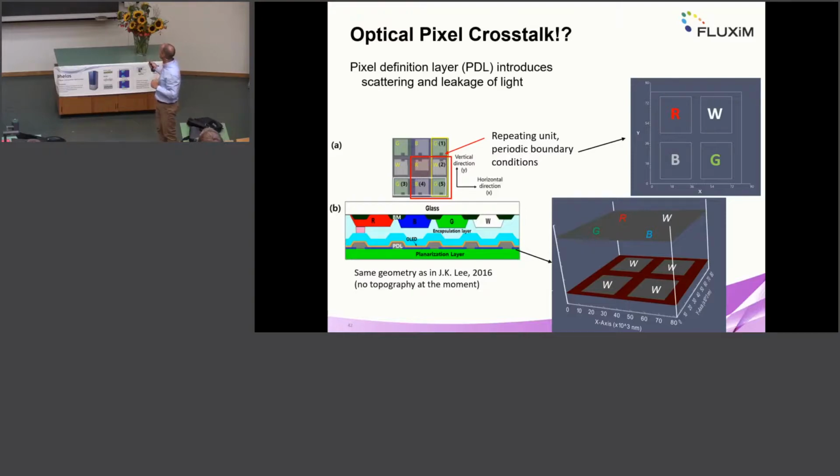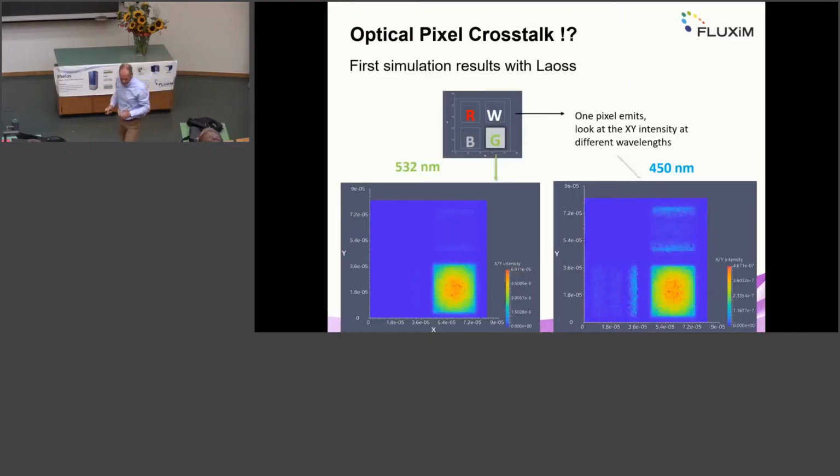Now if we turn on the green one, then we see that depending on the wavelength of light, we can check that some light, this is now the blue light coming from the green pixel, meaning that there's a white OLED below which contains blue light, and this blue light can escape through the white color filter and also through the neighboring blue pixel where we have a blue color filter.